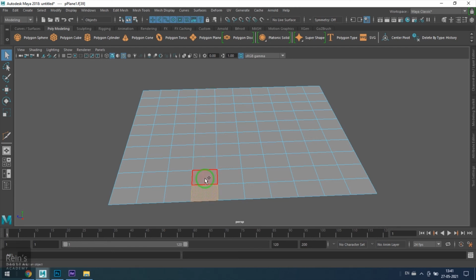So if I am selecting this way, this doesn't count as a loop, because when I'm selecting, the faces should be parallel to each other. Now if I select this one, this is not a parallel face for the previous selection, so this is not a loop, and a loop will always go that way.